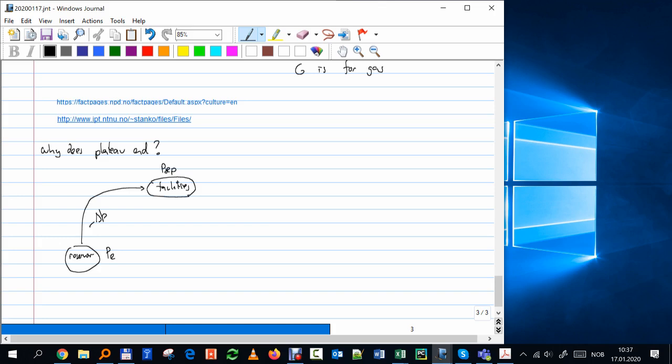By the way, how is that separator pressure? Is it constant or changing? If it's constant, why is it constant? If changing, why is it changing? Depends on the bottom hole pressure. Either we keep bottom hole pressure constant and produce at varying rate, or it depends on the friction factor in the tube. Okay, the separator usually, yeah, that's also true, but let's go.